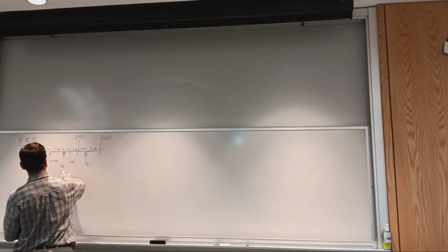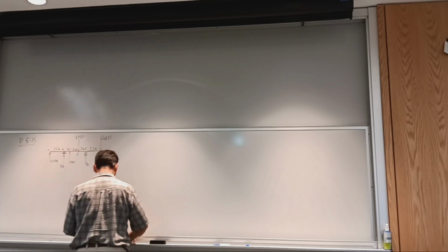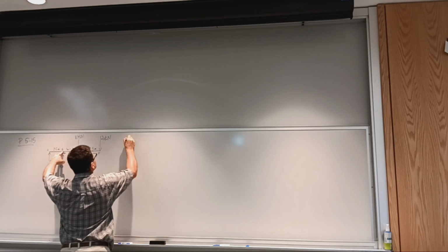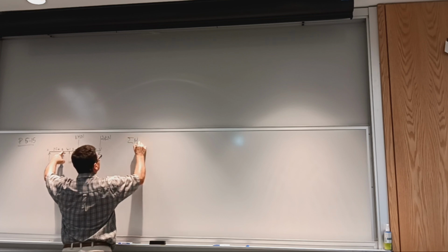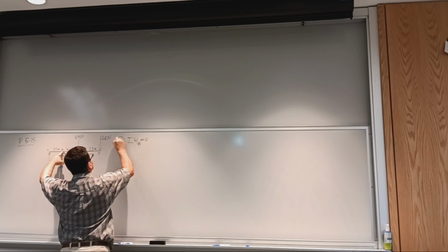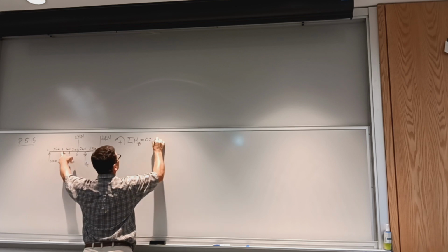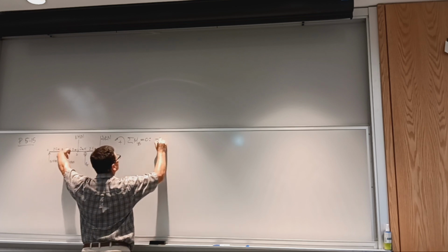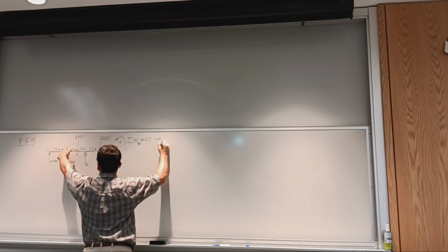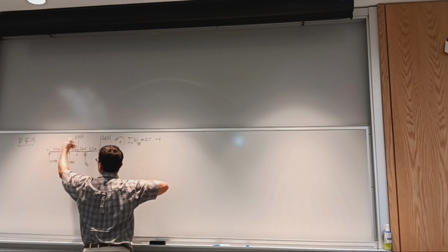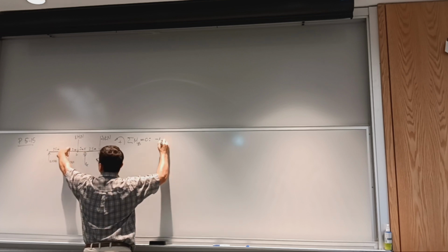So in order to calculate reactions at the supports, we need to sum moments about the supports, because it eliminates one or the other of the unknown reaction forces. So I'm going to sum moments about point B. And what do we write? The force at A generates a negative moment, so it'll be negative. And I work with kilonewtons. No, we're not doing stress analysis. So moments will be in kilonewton-meters, and shear will be in kilonewtons.